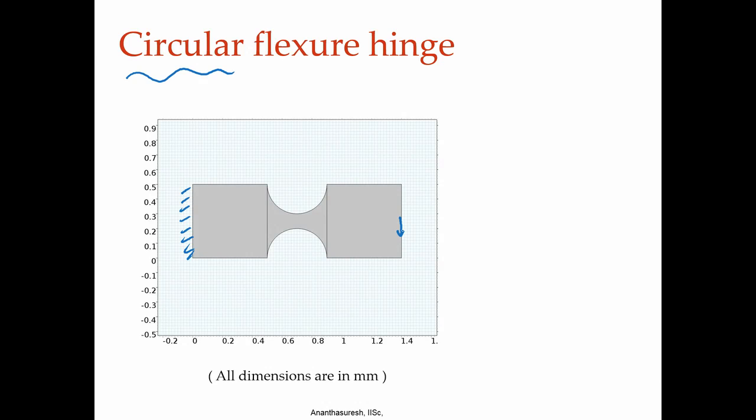The shape function selection is what you do when you choose different finite elements that are there in any finite element analysis software. There will be elements with some code name for it, and behind that are the shape functions. Lately, finite element analysis software actually gives you explicitly whether it is linear interpolation, quadratic, cubic and so forth, COMSOL finite element software being one of them. It is a new way of looking at it, so that you are mathematically more connected rather than blindly going by the element name. So, which elements do you take?